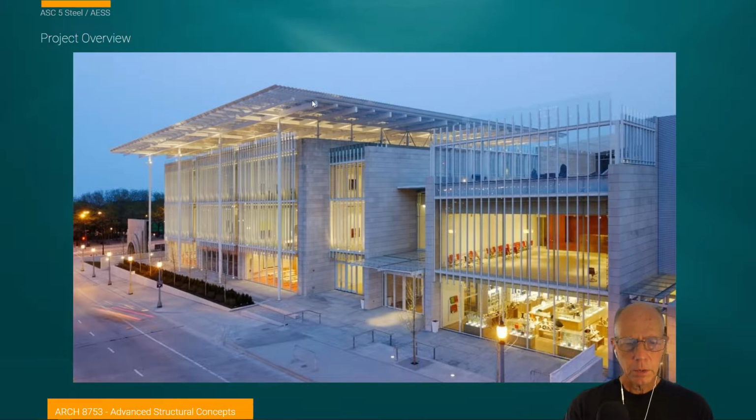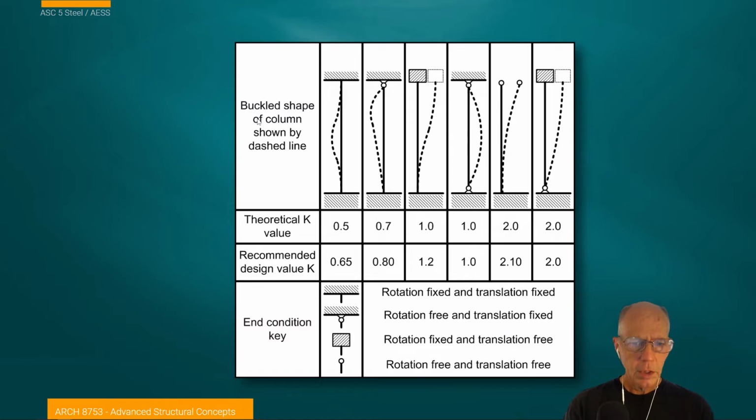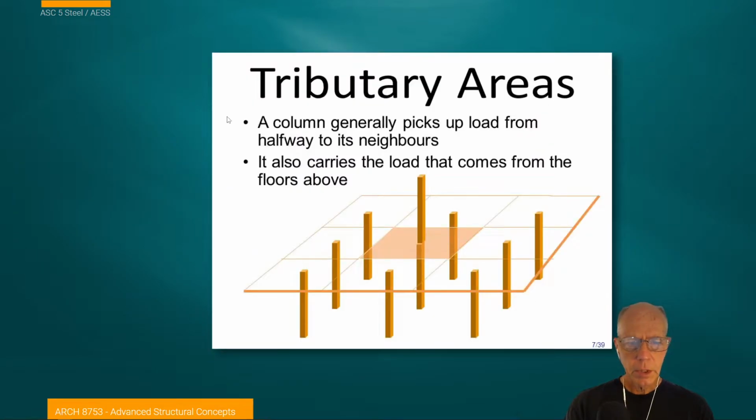And the whole crux here is to really lay out this grid system, to do some basic calculations about the strength that needs to be in this column system to support a load system, and kind of the thicknesses of those beam elements. So let me just jump back here right away, start with the conversation about kind of the review of this idea of tributary area.